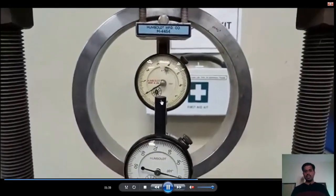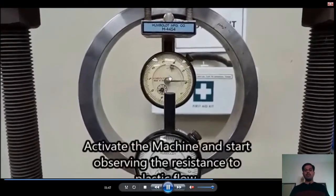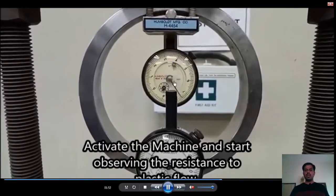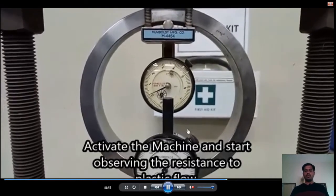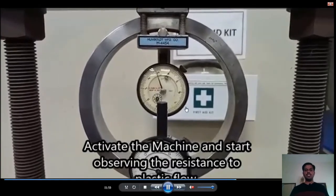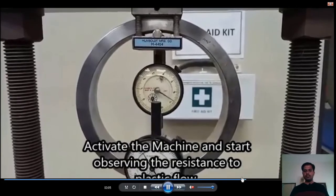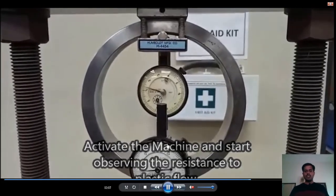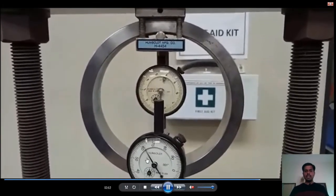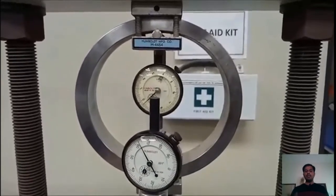So this is your micrometer, which directly converts the forces. Here we have activated the equipment. There are some forces acting. This force goes on increasing on your concrete. So this proving ring will try to deform its shape as soon as we apply the forces, and the deflection is also measured at this micrometer or dial gauge. As soon as the dial gauge stops, there will be no deflection.